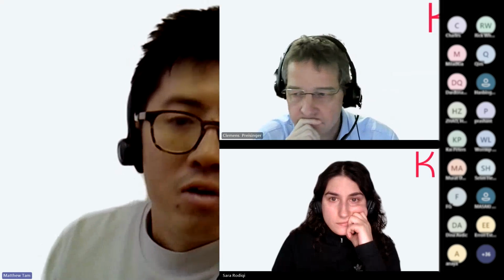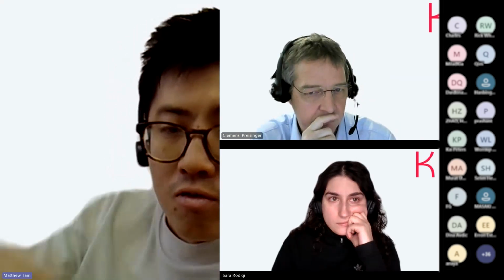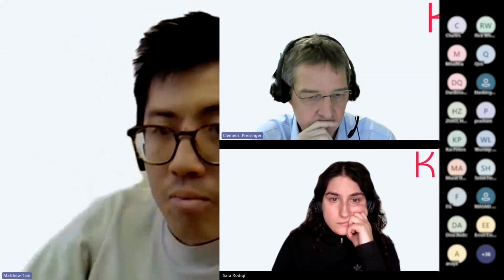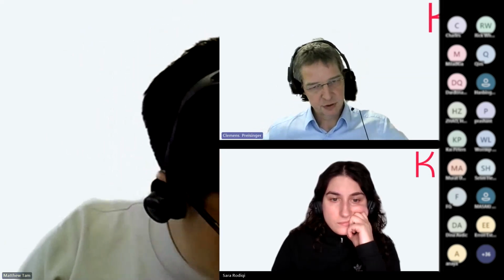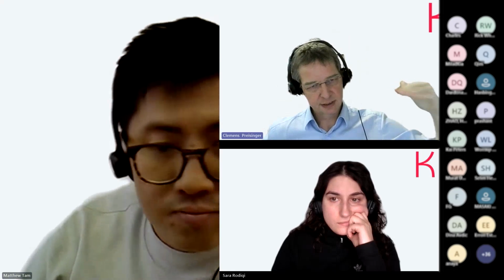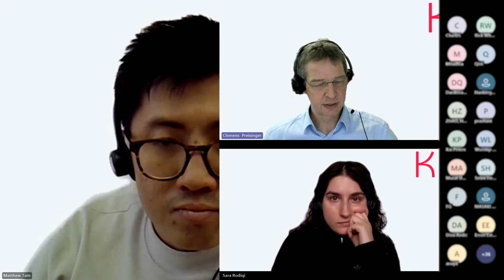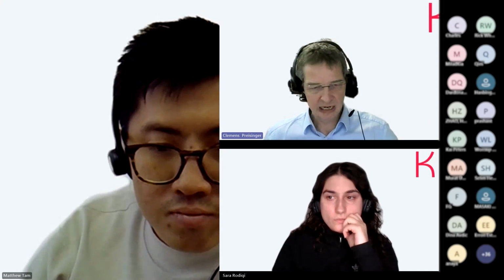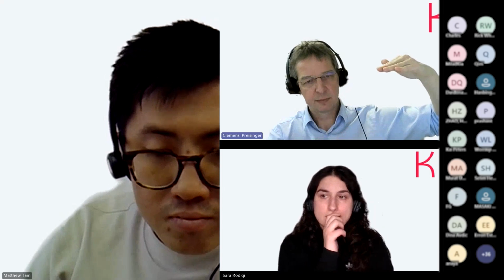And the order of the cross-sections is also very, very critical, because basically Karamba goes down the list from top to bottom too. It assumes that the best cross-section comes first, and then the next best, next best. By default, the cross-sections in the cross-section library are sorted by their height and not by their area.